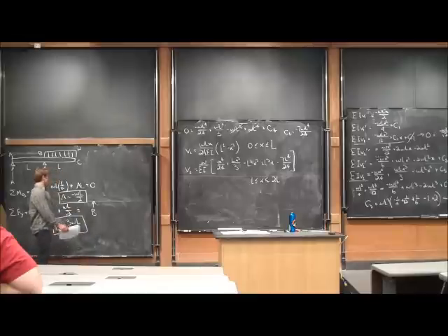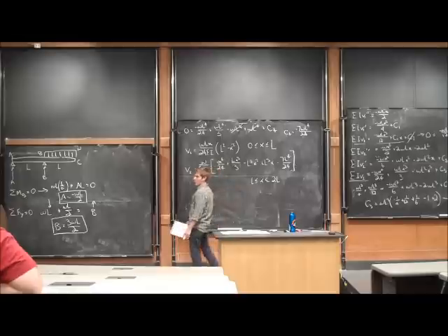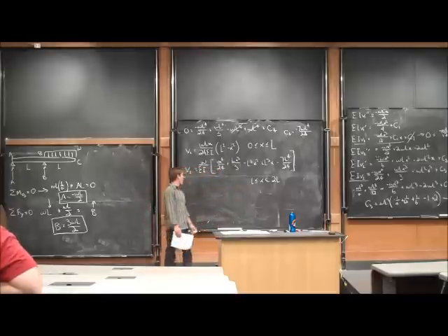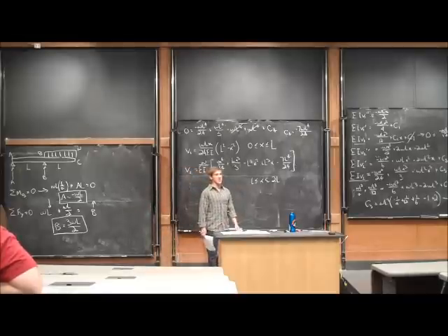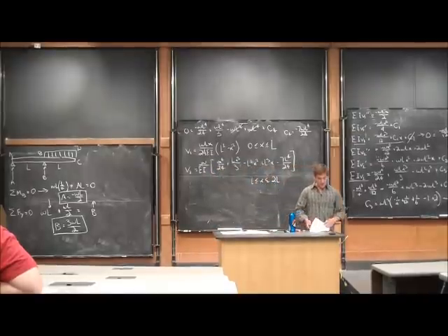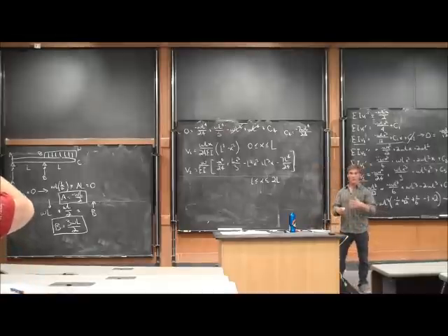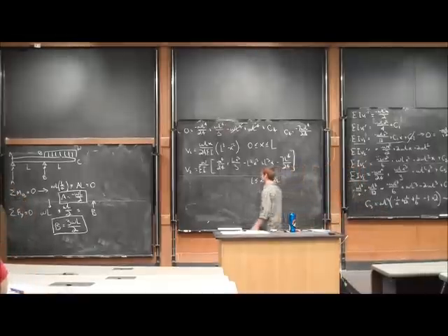So you can see that from this loading, we can find out what the deflection is at every X location along the beam, and then by substituting what our actual physical values are in for L, E, I, and W, we can actually find the deflection at any given point. We can then design to make sure that we're okay with that deflection, or that we are designed to be able to withstand that. We have proper clearances in our beam or truss system.